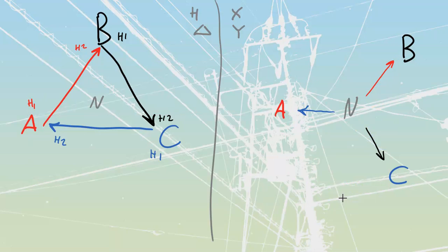And now we have got our Y type of connection over here. Remember that the ones are going to be the tails, and the twos are going to be the heads for each of these. So now that I know that, I can place in my connections. My lines, so I'm just going to erase this neutral point here in the very center, and we'll extend these out just a hair over here, just to make that actual connection.